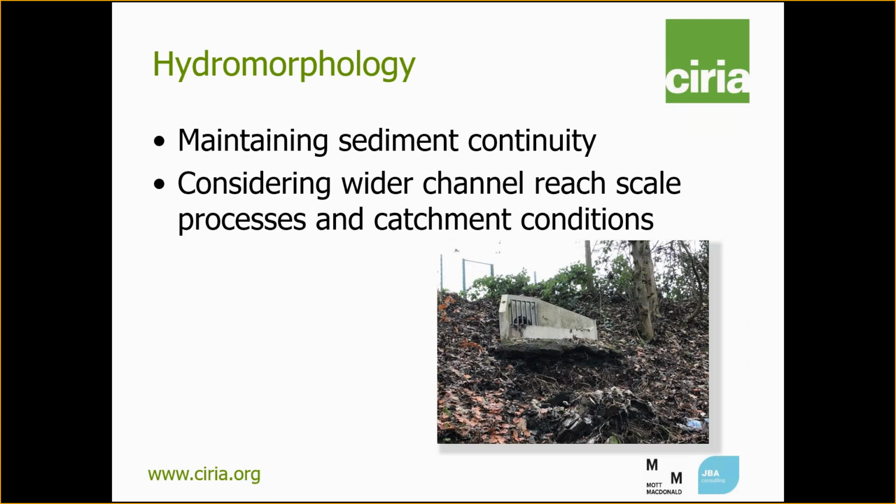It's also important to understand the river when assessing the potential effects of a culvert, screen or outfall, whether it's being constructed, modified or removed, and also the impacts of blockage. So we need to think about the river type, the catchment history, its flashiness, sediment supply, the composition of that sediment and the dominant sediment processes. And without this knowledge, an unintended channel response could occur.